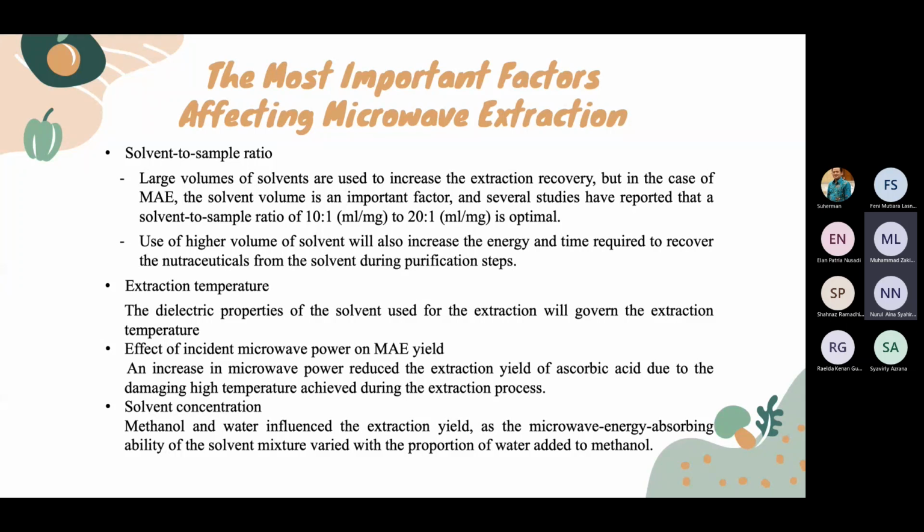And use of higher volume of solvent will also increase the energy and time required to recover the nutraceuticals from the solvent during purification steps. Another factor is extraction temperature. So the dielectric properties of the solvent used for the extraction will govern the extraction temperature.